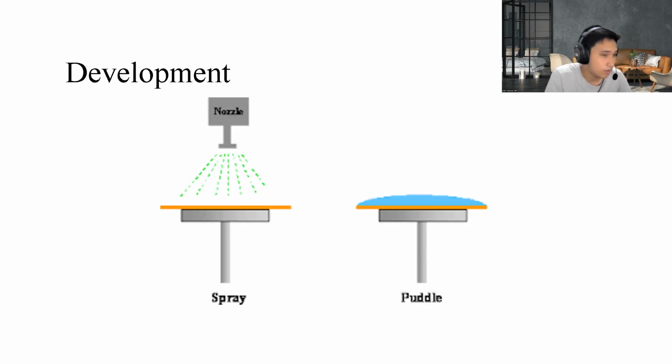The last one would be development. The step after exposure is to spray developer on the wafer in order to remove the photoresist in the area not covered by the pattern so that the printed circuit can be revealed. After the development is completed, it needs to be checked by various measuring equipment and optical microscopes to ensure the quality of the drawing of the circuit diagram.